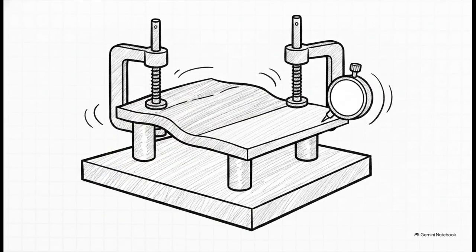Picture your weldment clamped into its checking fixture. The rough points hit the datum targets, it flexes into its functional shape, and suddenly, it passes inspection. The clamps simulate the installation bolts. The twist from the welding heat is just pulled right out by the physical restraint, and you can measure that finished machined mounting face perfectly relative to your datum targets.